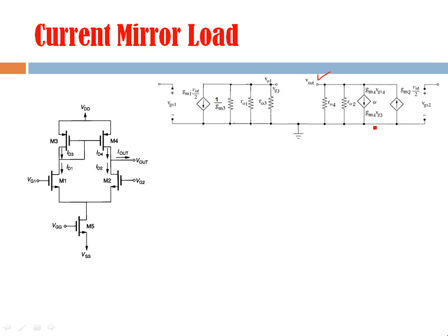So if we want to solve the right side part, we need to solve this one also, because only then will we be able to find out the voltage here, and that voltage will be used to find out the current in this component, and only then will we be able to find out the voltage, right. So we cannot omit any part here, left side and right side, both we have to include. But yes, we can ignore this part, because that input side is not going to be used in the frequency response solution. Only the output terminals we need to solve.